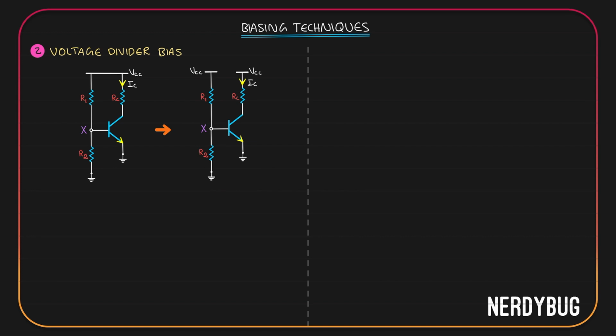Let us take it out. I am going to draw the Thevenin equivalent of this circuit. Output is taken over here. We are giving VCC over here. VCC is basically a cell that is connected like this that goes to the ground. So I can draw the same circuit like this. VCC is modeled as a cell. Its positive terminal goes to R1 just like over here. R1 goes to R2 and then it goes to ground. Here also same thing happens. Between R1 and R2 we are taking the output. Here also between R1 and R2 the output is taken.